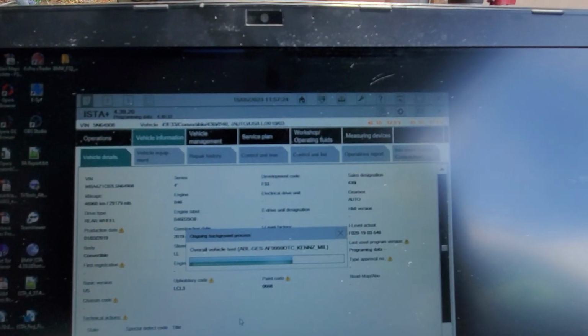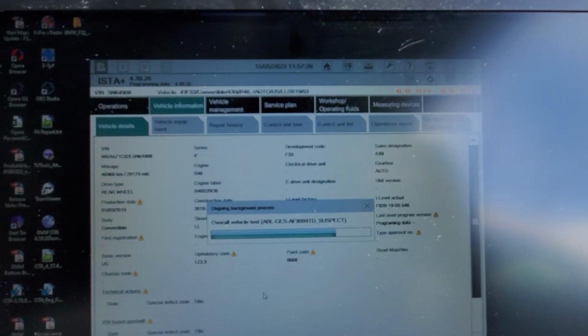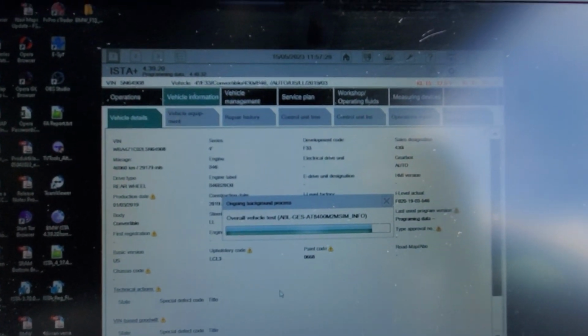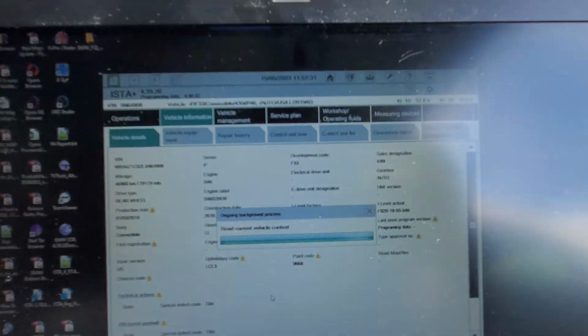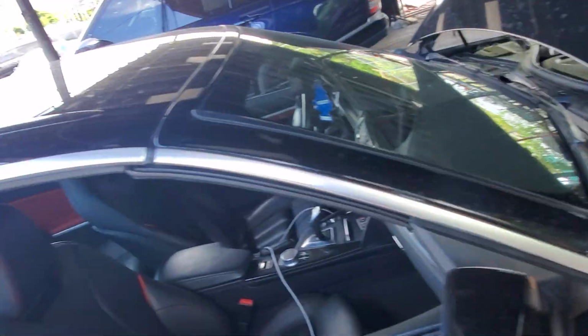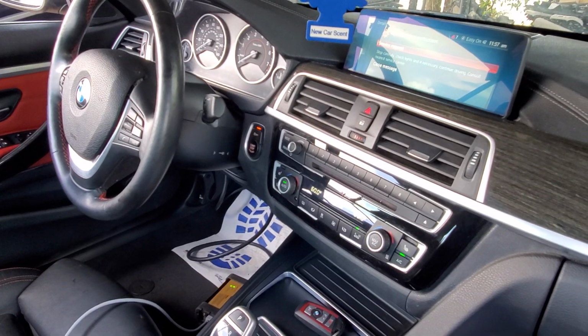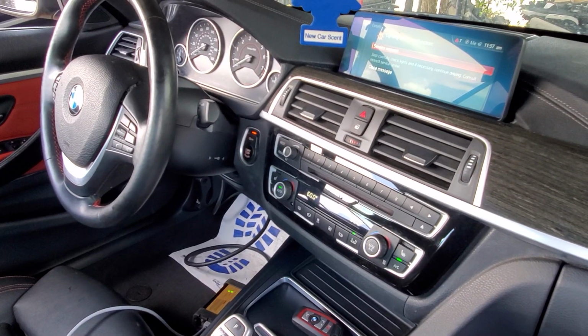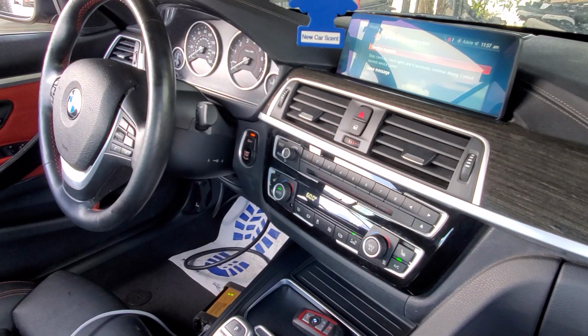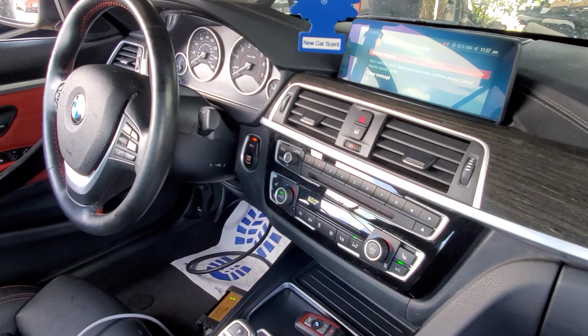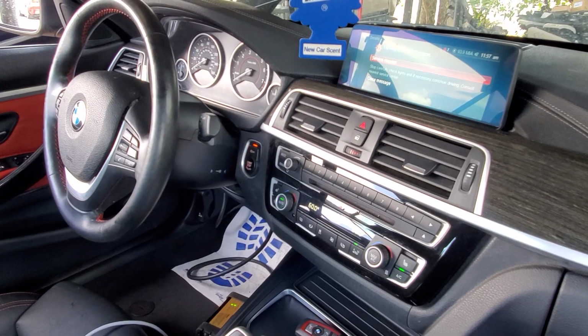Alright, okay YouTubers, whenever you're on any BMW, like say an F series or G series, and you turn on the ignition and it shortly thereafter turns itself off, it's because it has a battery management system that keeps track of the voltage, the startability voltage threshold that must start the car whenever the owner or the driver is ready to drive away. That is why it turns off on its own.